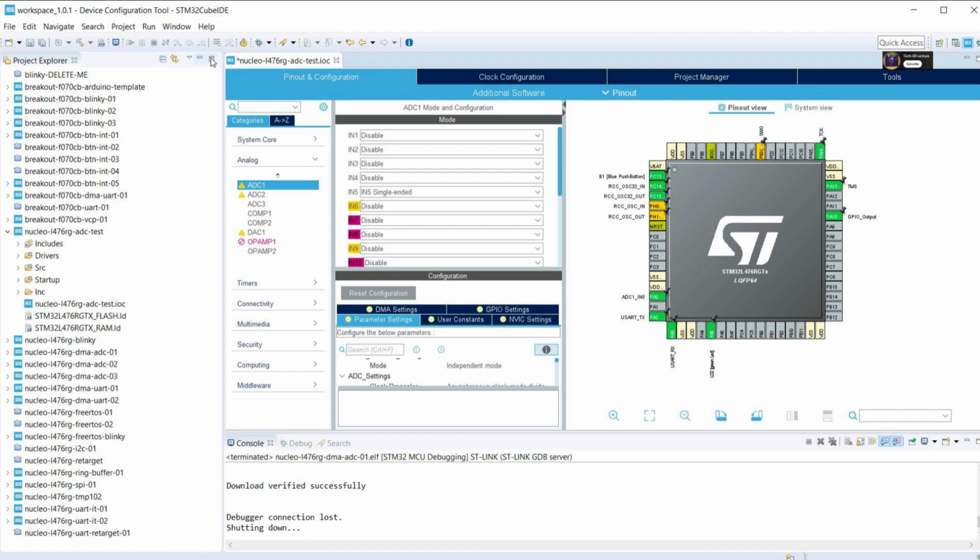Okay, so CubeMX sets it all up. Then what? Then you generate the code. CubeMX writes the low-level initialization code for you, typically in a function like MX_ADC1_Init. This generated code sets up the ADC's internal configuration registers based on your choices: the handler structure, clock prescaler, resolution, continuous mode setting, data alignment, number of conversions, DMA settings if enabled. And then it configures the specific channel settings, like which channel it is, its rank in the sequence, if scanning, and that crucial sampling time.